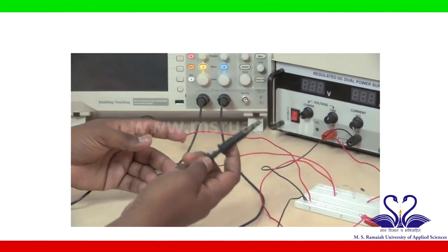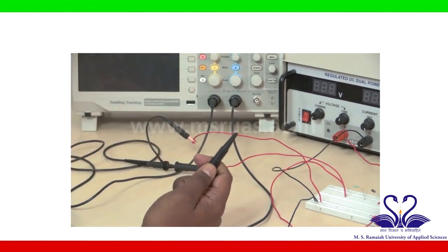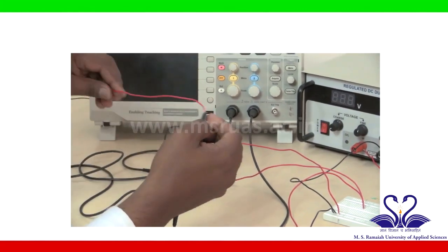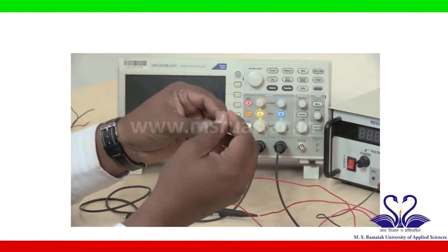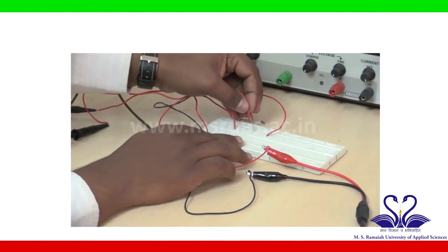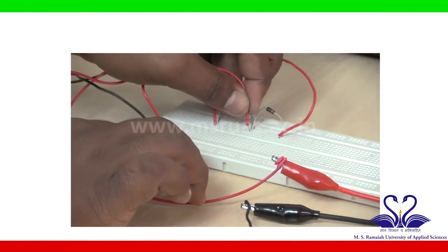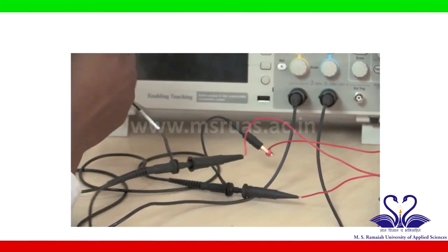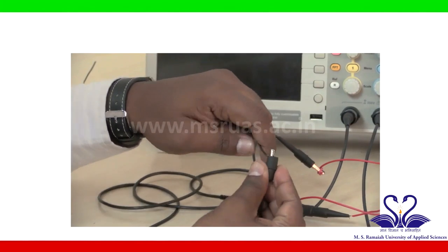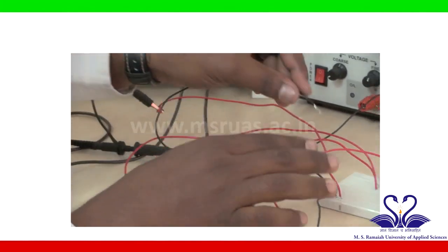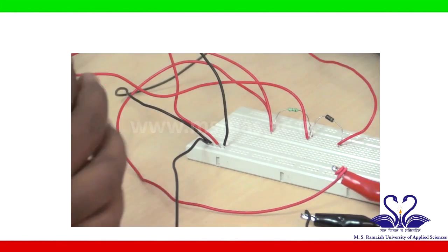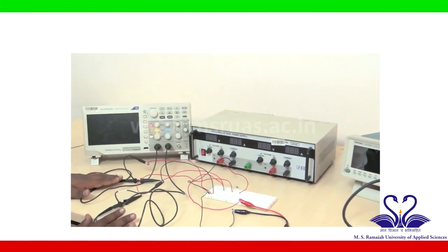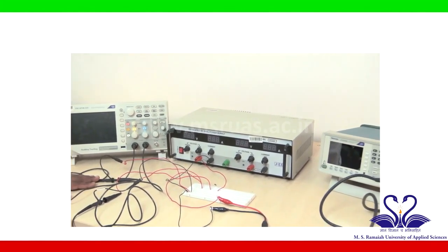Now, channel 2 again has a positive and negative. I will connect channel 2 to the output point, where the output is to be observed or measured. So, this is the positive of the second channel, which is connected to the P side of the diode. This is the P side of the diode in the circuit, and this is the negative of the second channel probe, which is connected to the ground. I will connect this to the ground on the breadboard. This completes the circuit connection of a positive shunt clipper circuit.